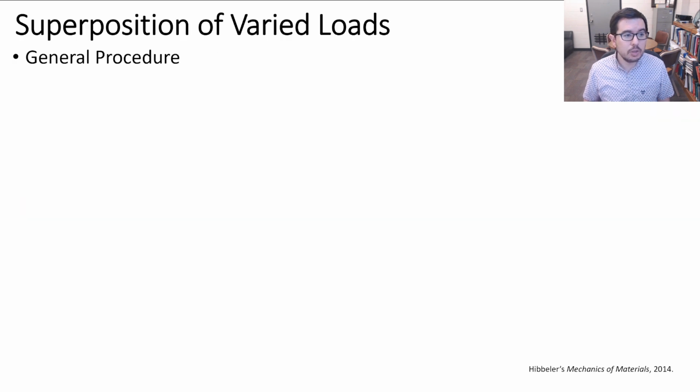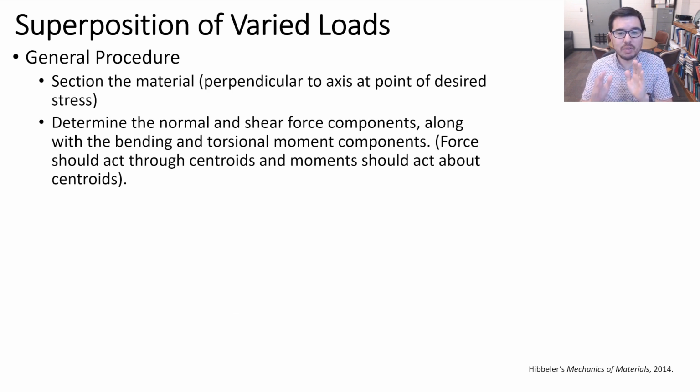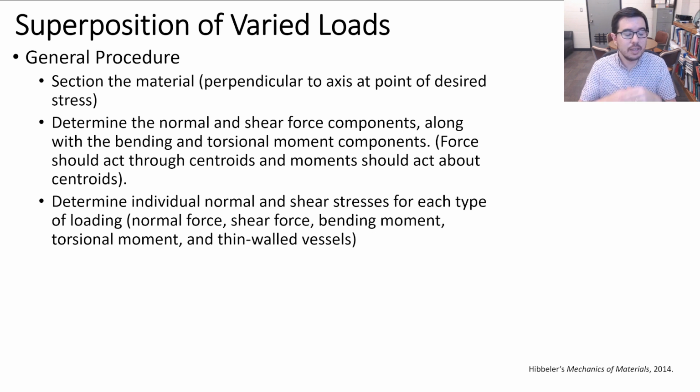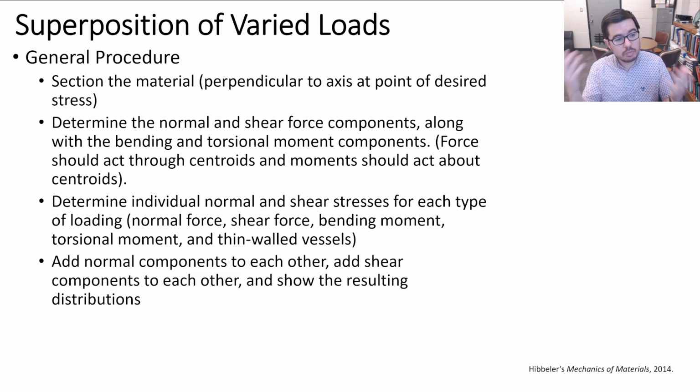Okay, so this is the same procedure. Now we've seen it twice. Section the material, determine the normal and shear force components at that section, determine normal and shear stresses at that section. And in this case, we're looking at shear stresses for this portion. And then we add the normal components to each other, or the normal stresses, and add the shear stresses together. So in this portion, we're looking at adding some shear stresses to each other.